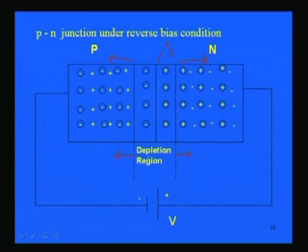And if we look from the barrier potential point of view, or the built-in potential point of view, the built-in potential polarity is positive this side and negative this side, and we now have this voltage applied with this polarity, negative to the P and positive to the N. So, now the barrier potential will be increased, from Vbi earlier to Vbi plus V now.